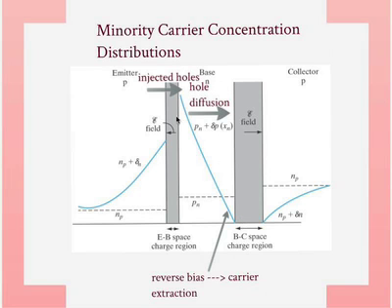So if you look out here, just concentrate in the middle, which is the base. This is the excess hole concentration. You have excess holes over here at the interface, very high, like I drew here, and they will quickly diffuse and recombine. And on this end, you have very low. It's negative. It's below its equilibrium concentration because carrier extraction is happening. That's the only thing we need to know. That's the steady state carrier distribution of holes within the base region.